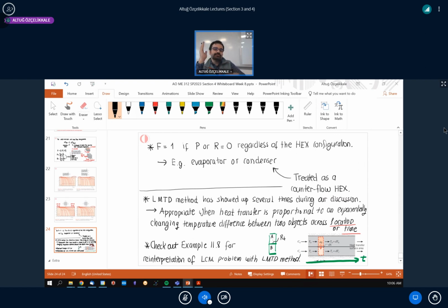It turns out that this example problem was actually touching on the lumped capacitance method. And we formulated the problem by writing two lumped capacitance equations for two slabs A and B, subtracting them so that we got the temperature difference. But then the problem reduces to, I'm sorry, log mean temperature difference. So you can actually look at the example problem. It's the exact same solution as was expected in the midterm question.